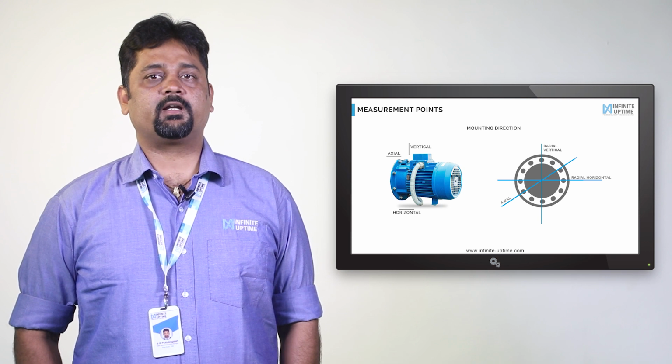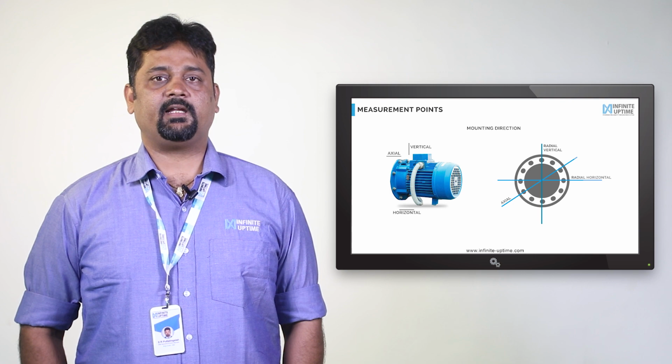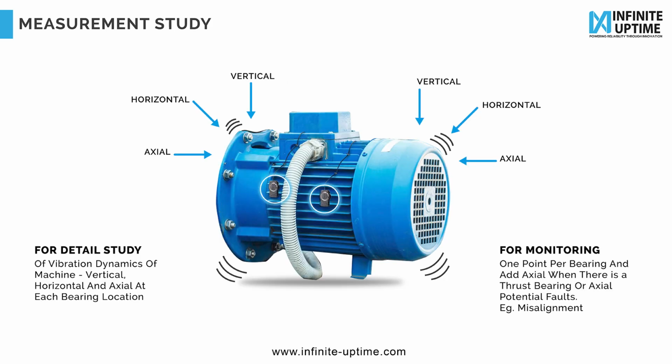It is also very important to choose the best location for vibration data collection. Ideally, it should be closest to the bearing location. Machine vibration may be in any direction depending upon stiffness and damping characteristics. As shown in this diagram, horizontal location is always chosen in a position where stiffness is weak. We need to monitor in all three locations for each bearing location of the component. Or, even easier, choose an IoT predictive device to measure all three axis data together.